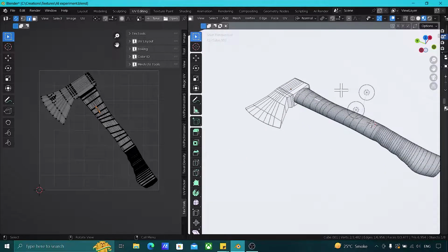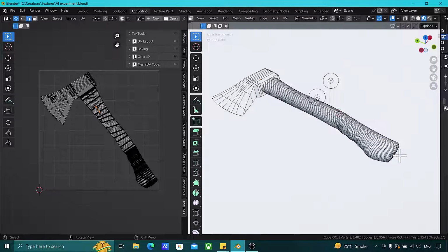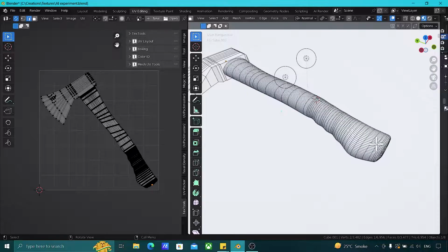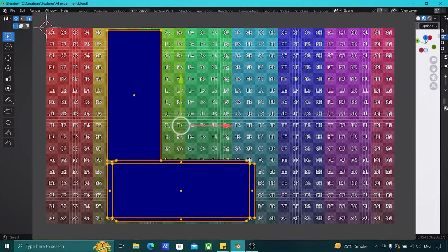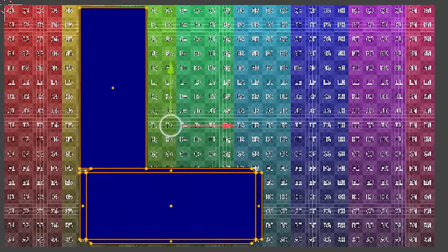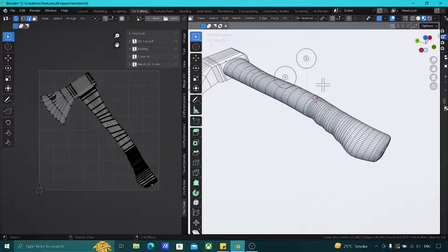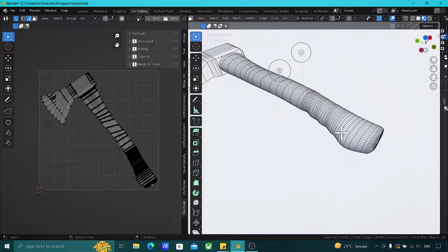You need to understand the flow exactly. The principles are the same. If there is a wooden texture, it will probably be going up in a straight direction, or if you are choosing it to go in a sideward direction, make sure every face of your object is following the same criteria. It's not that a few faces are going up and a few are going sideways. No, it won't look realistic, and it is not a feasible option as well, and it is very criticized in real world projects. So make sure that your UVs are aligned properly.